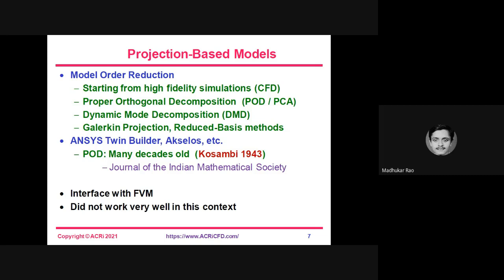And I did not use ANSYS Twin Builder. I just wanted to mention that to say that these tools also have reduced order models in them. I interfaced it with the finite volume method, and we got a good fit to the overall model, but when we interfaced it back with the finite volume, we had a lot of difficulty maintaining the stability of the solution. It did not work too well.